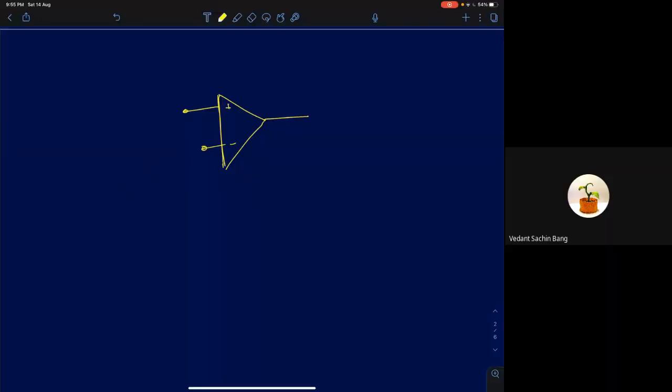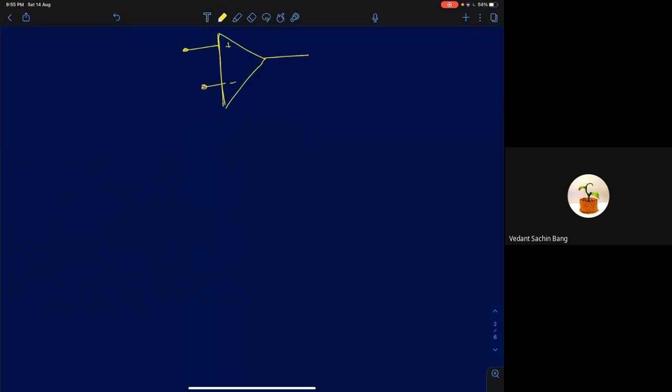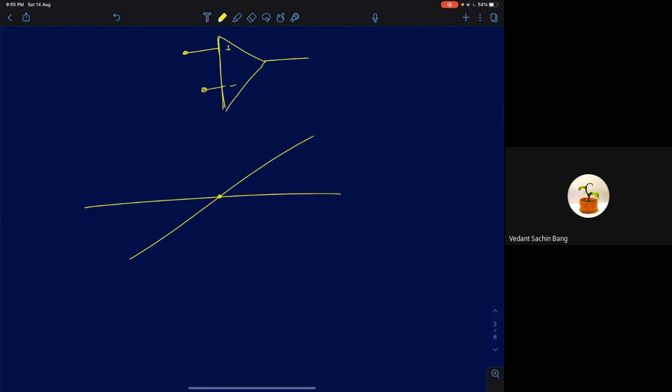So now we will look at, so we'll see if there are any problems with this implementation. I can directly use an operational amplifier in open loop and it perfectly works. Now, the operational amplifier fundamentally operates on the principle that if your input is greater than 0, I'm drawing the sine wave and this is the 0 level. If the input is greater than 0, then the output will become plus V set.